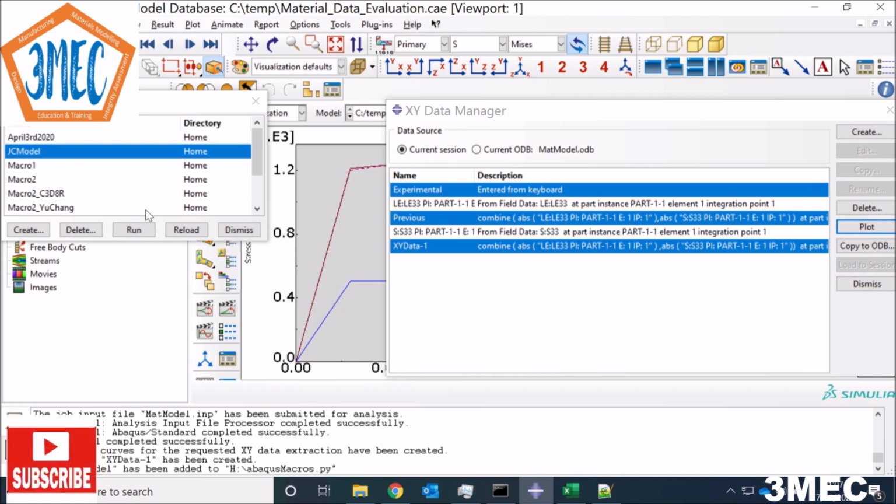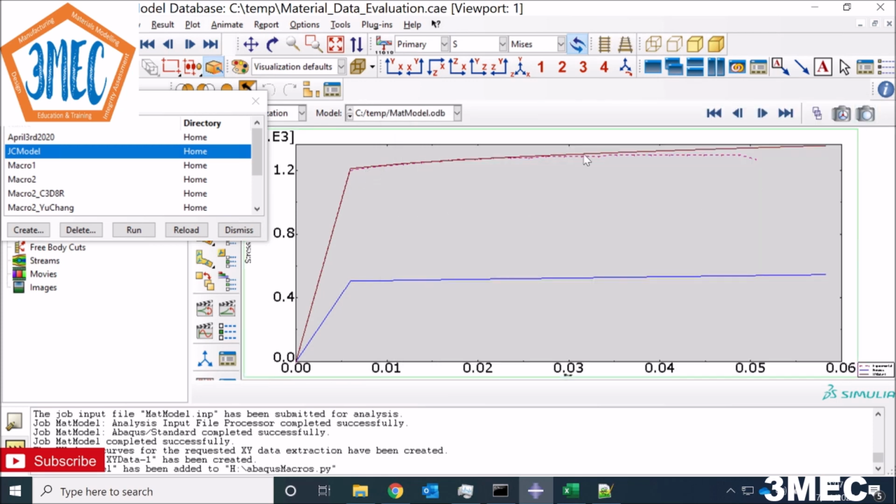So now this process which we did just now for post-processing is just one click away, and I will prove to you I'm correct in that sense. All right, so I have plotted those after changing the parameters, and you can see I'm very close to the experimental curve now by changing the set of parameters. So by changing material parameters, you can also fit the model. And once you are happy with the fitting, you can say that these are my final set of parameters.